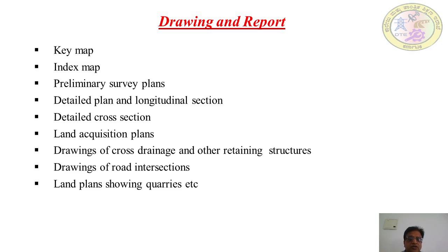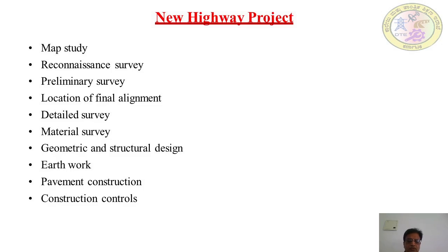Land plans for showing the quarries: even the material we get from the quarry, whether the soil quarry or the aggregate quarry, we need to show the location, how much is the distance, how much is the traveling time, all those things you need to show. So those are the drawings and also the report that you need to prepare for a highway project.